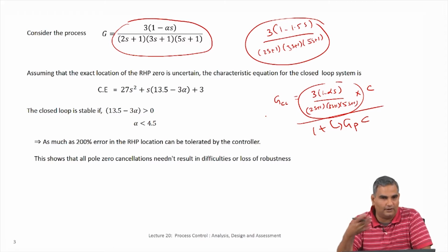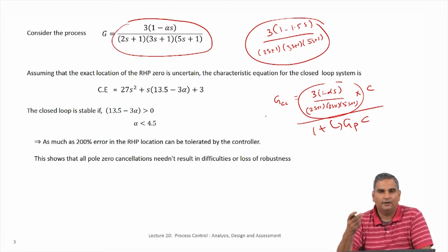Okay. So, that is already incorporated, and even after this accommodation I will not exactly get what I desire because of the plant model uncertainty. So, the first is actually making allowance for the difficult to control components in the model, and the second thing is when the actual process is slightly different from the model, then you lose a little more performance.